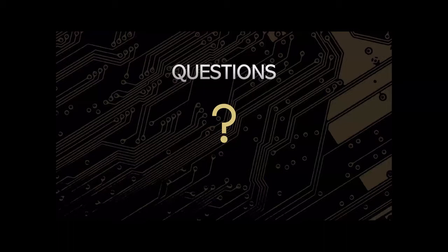From Torge: if I have a design with different assembly variants, is it okay to provide one generic pick and place showing all components and then specify each assembly variant through separate variant specific BOMs?